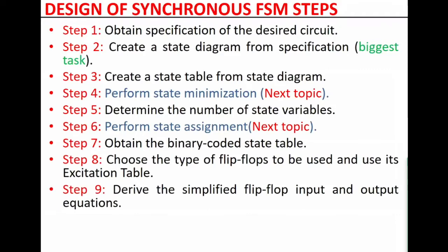In the analysis, we had the flip-flop input. We are looking for the next state. Here, by the time you have a state diagram, you know the present state, input, and next state. So you are looking at flip-flop inputs. That's the difference. Then you draw your logic diagram. So those are the steps that you do in designing synchronous finite state machines. From now on, we're just going to look at examples. And the first example is the basic one, that I will go slowly and take as many questions as you will ask.